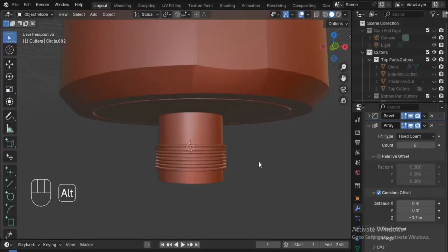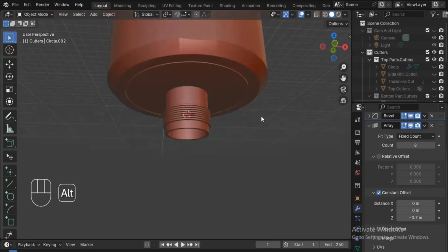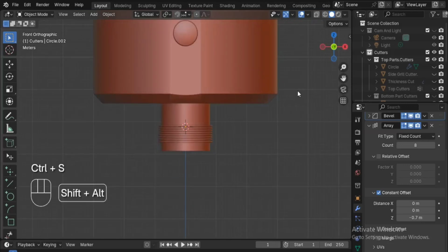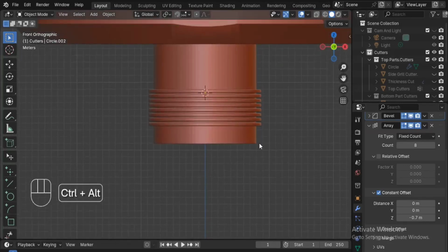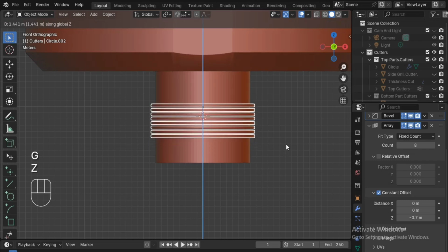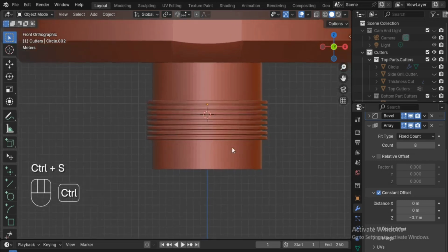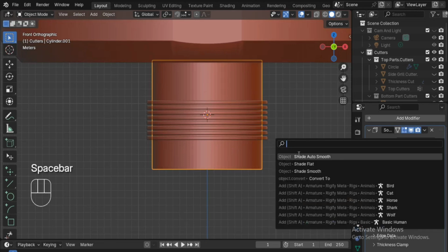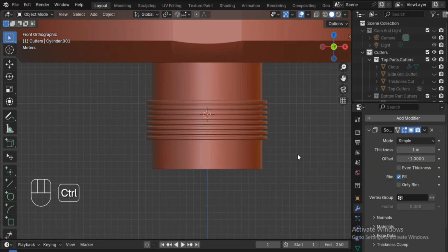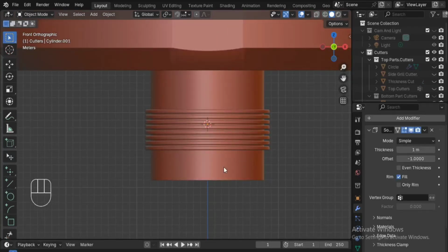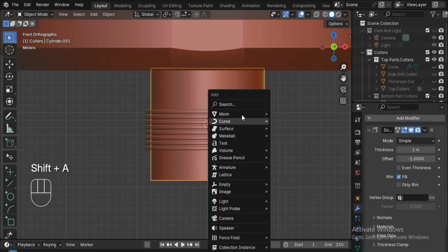And add a bevel modifier to have more profound edges, and always check the hard normals option in the bevel modifier normal stack, and change the constant offset to 0.7. And then we're going to add 8 arrays of this, 8 copies of this ring, so it just looks right.